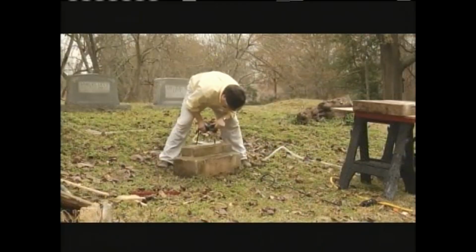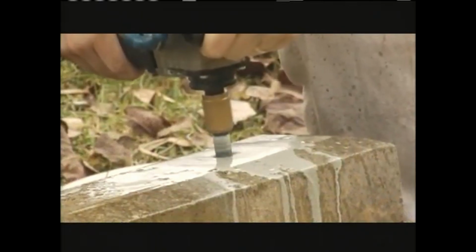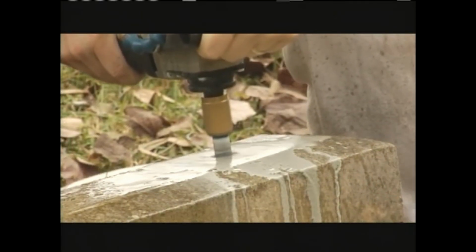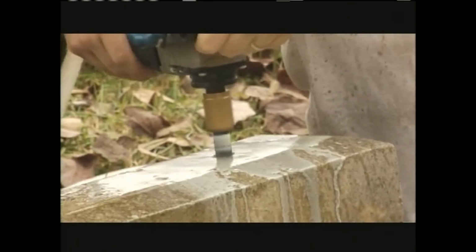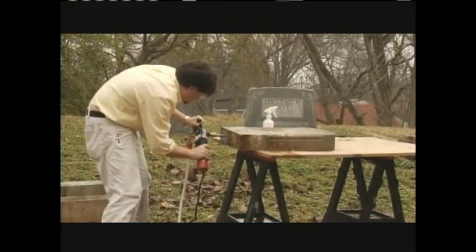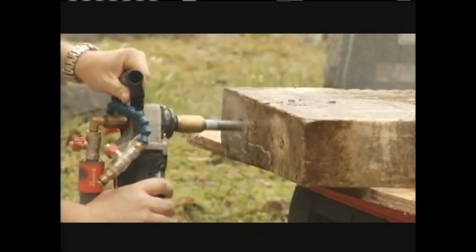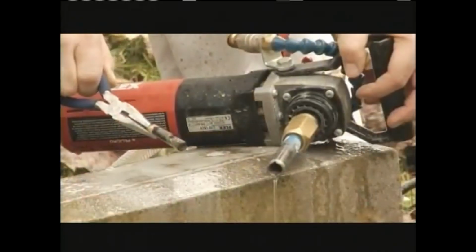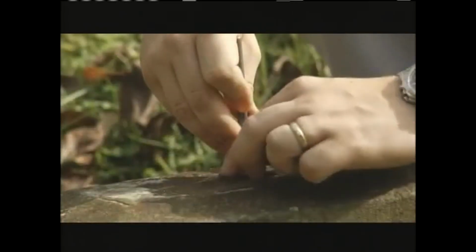We will do that with an electric angle grinder fitted with a masonry coring bit. Masonry coring bits are also available for standard drills. When choosing the coring bit to use, select the one closest to the size of the original hole. There is no reason to remove any more original material than is absolutely necessary. This procedure will need to be done on both the base and the headstone. Once the pins are removed and the hole is cleaned out, we need to measure the depth and diameter of the hole.